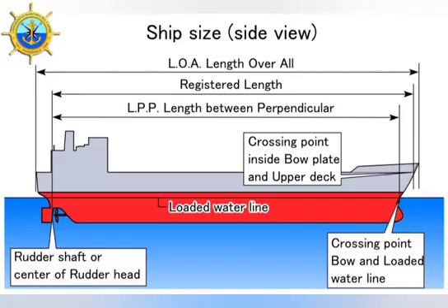The ship's midline acts as the ship's axis of symmetry on which the transverse coordinates of the starboard and port side are measured. It also tells us the design waterline, forward and after perpendicular, length between perpendiculars, length overall, longitudinally, transversally, vertically, etc. There is currently a great variety with regard to the size and type of ship, but in terms of the construction system of their fundamental structures, they respond to three basic construction systems: transversal system, longitudinal system, and mixed system. Nautical vocabulary is an essential part of knowing a ship.